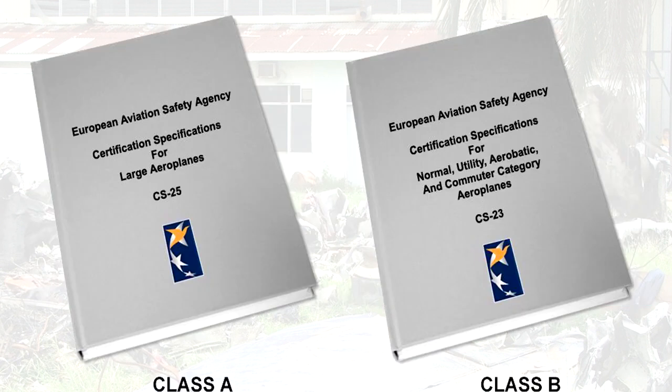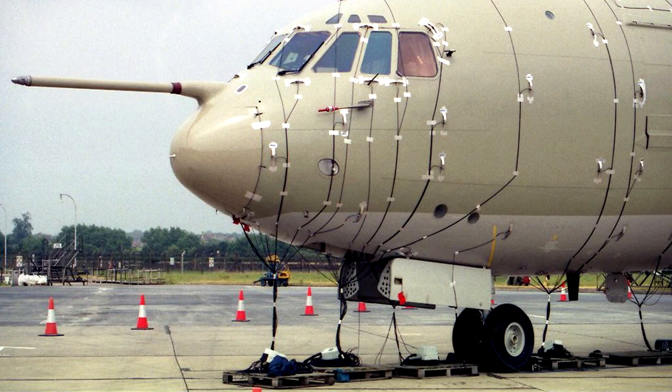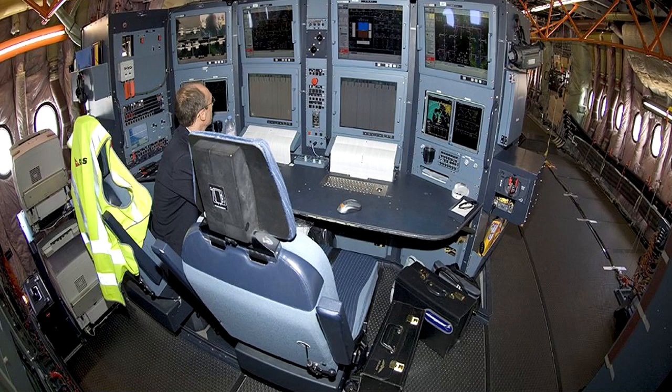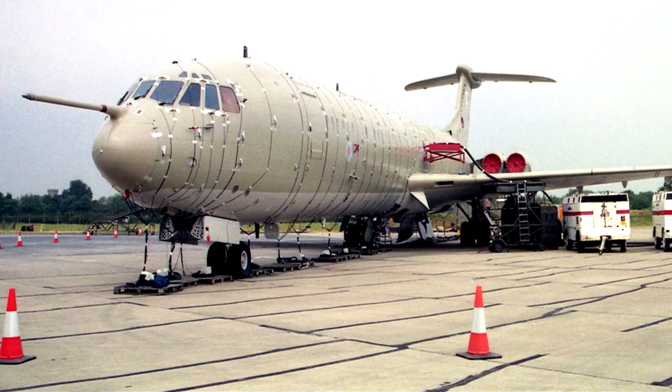Aeroplane manufacturers must abide by performance regulations laid down by the authority in order for the aircraft to be given its certificate of airworthiness. For example, large aeroplanes, principally Class A aeroplanes, must abide by the certification specifications laid out in EASA in the document CS25, and Class B must abide by the certification specifications in CS23. To achieve this, rigorous testing of the aircraft must take place by the manufacturers. It is a very lengthy and costly process, but one which is absolutely vital for safety.